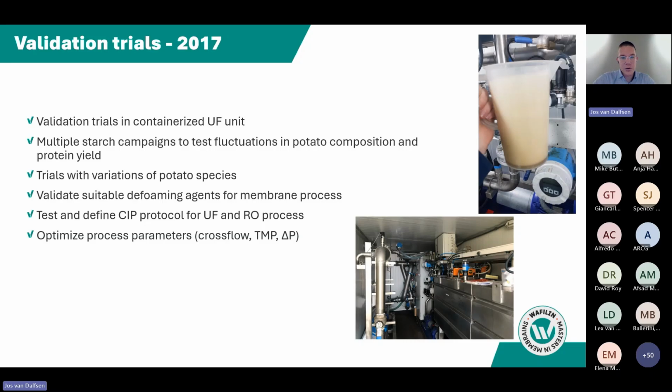stream with a high solid load, fibers present in the fruit juice that we have to deal with. So we selected tubular membranes for this application for protein concentration, but also knowing that the residue of fibers is still present. So we built a containerized unit together with Berghoff, selected the membranes for the trials, 8 millimeter membranes,